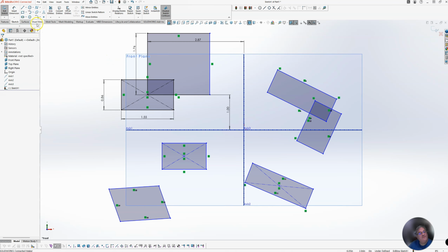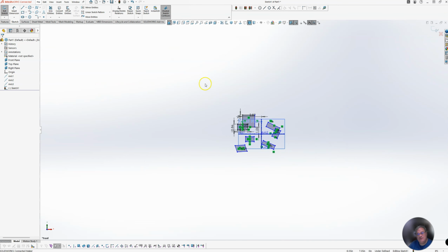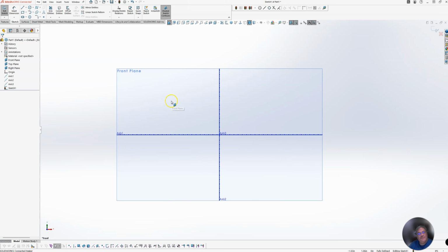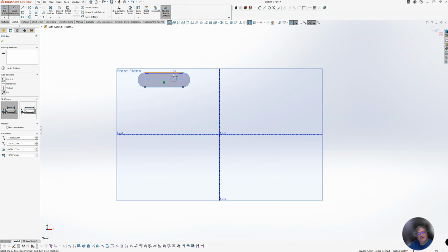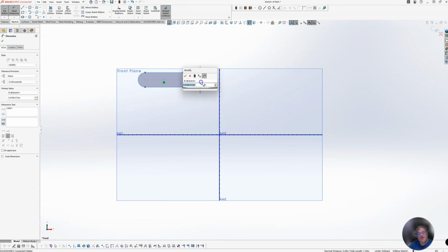So now, let's just go ahead and clear our board again. Selecting everything, hit delete key. We're still in sketch mode. Now slot. Slot's kind of fun. First one, center, didn't give you a diameter. Obviously you can dimension your overall. You can dimension center line.